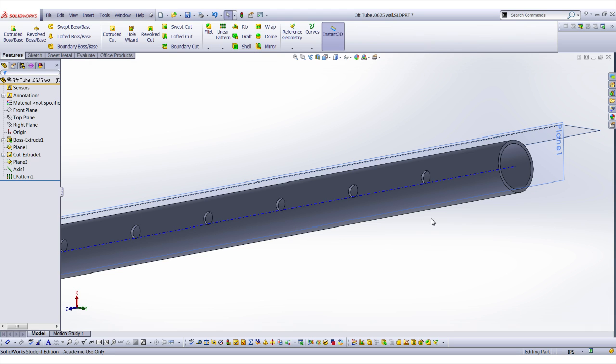Alan, we're gonna have to figure out what happened. I created a flute and I saved it as something different from my whole model. Can I go back? Only by suppressing that feature. You can right click in the feature tree, find the part or the couple of features that are holes, and you can suppress them.